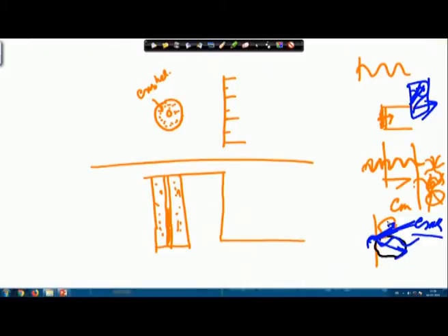So, the cracks will have differential motions, creating shear along the crack, and the crack will be widened. If there is heterogeneity in the rock, shear will occur at that contact position and new cracks will be generated. So, in this way, the rock fails under shear in this position because of the wave propagation.